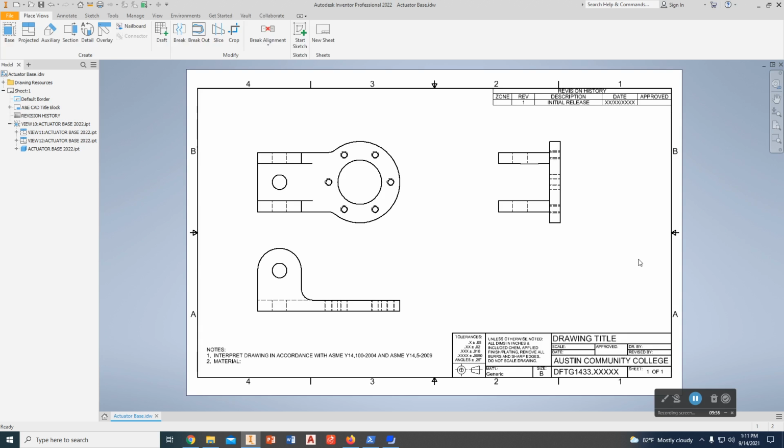This is just a regular view, so you're going to go to here and then pick on this view right here. Now just move straight down and pick. Now right click your mouse and choose create. Now double click on this view right here and turn off the shading. Just click on that right here and pick OK. There you go.